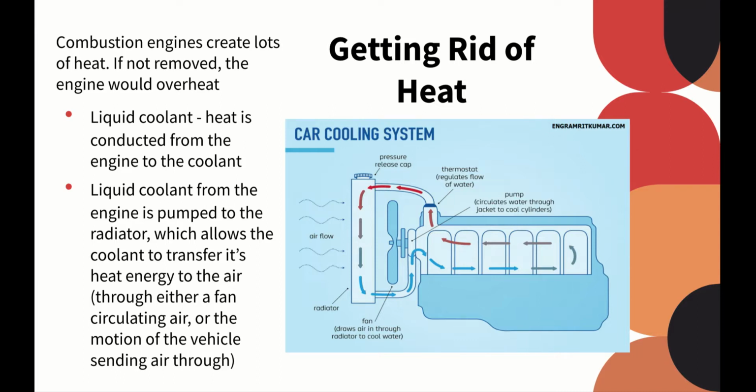In the radiator, air is allowed to flow in, and the coolant transfers the heat energy to the air. And then that cooler coolant returns back to the engine and starts the cycle over again. So this liquid helps to transfer energy away from our engine, keeping it at a cool temperature and allowing it to function and continue to run over a long period of time.